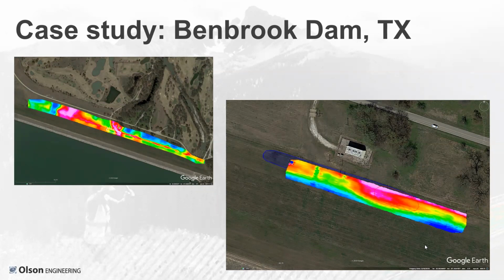The anomalous areas correlated very well with both the standing water observed there during several heavy rain events, and with all of the buried utilities that are in the dam. I was really surprised with how useful this was, and had I thought about this earlier in the trip, I would have probably collected a lot more data with it, but I didn't start it till the end of the trip.